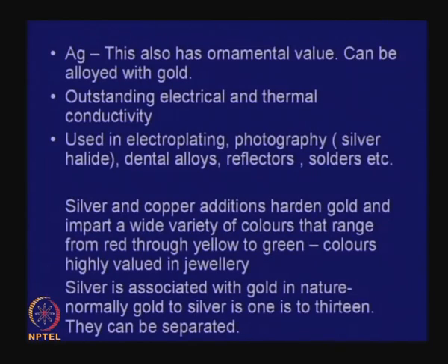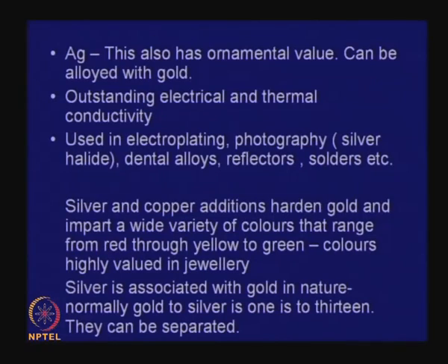Silver and copper additions, as I mentioned a little while ago, harden gold. Pure gold is not good for making ornaments, because it is too soft. So, some impurities in the form of copper and silver, when added to gold, make gold more useful, so that it can make ornaments. But additions of silver and copper impart a wide variety of colors that range from red through yellow to green, and these colors are very highly valued in jewelry.